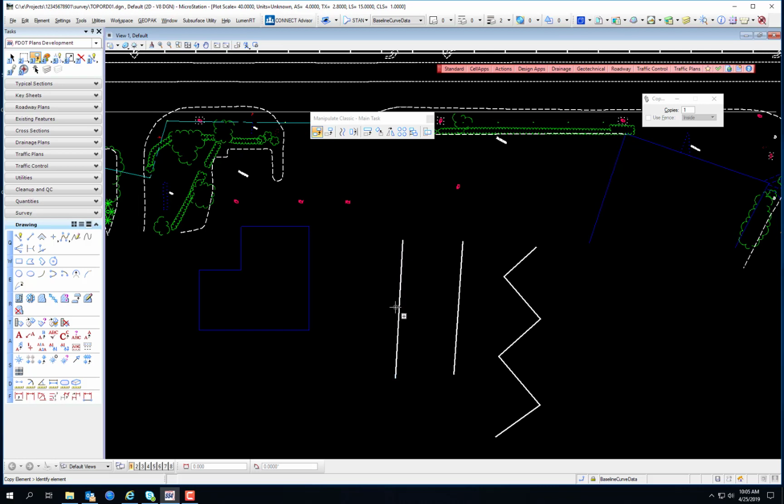You can select a key point, snap point on the element, and then notice how AccuDraw is active. So if you want to copy an element 5 feet, you can enter 5 into the X. See the X field down there? And you can lock that axis too. Oops, I did not lock the axis. Now, there the axis is locked. Okay?